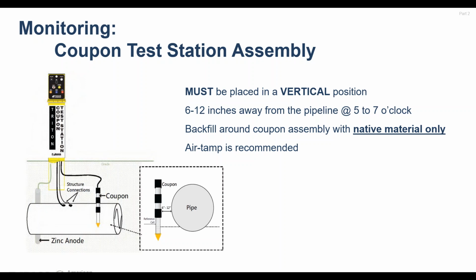So in other words, if you're using a hydrovac, for instance, and you've got this mix of muddy water, you probably want to make provision for some dry backfill material that's either from a nearby location or is very, very close in composition to what's around the pipeline itself. You'll see us recommend air excavation in most cases. Air excavation allows us to reuse that backfill material.